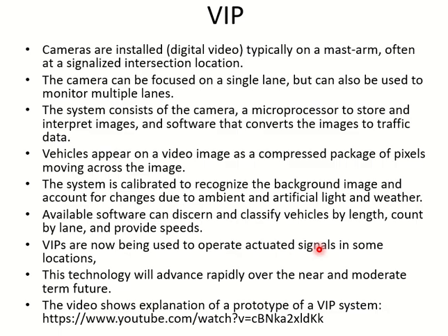Okay, so you will do some trial runs in which the software will detect different images, and then you will classify it. When you detect this size of the object, put it as a car. When you detect this size, put it as a truck, and so on and so forth. Another important thing for calibration is the background. Okay, so we can have a black color car, and we know the asphalt pavement is also black color, and we can have a gray color car, and we can have the light pole which is also gray color. Okay, so this is another sort of calibration.